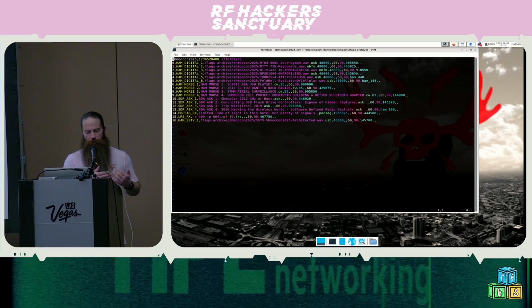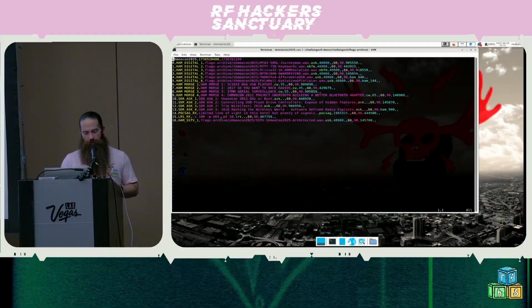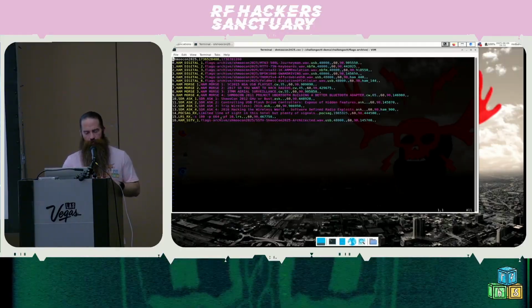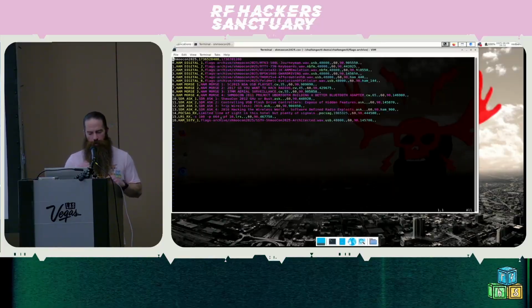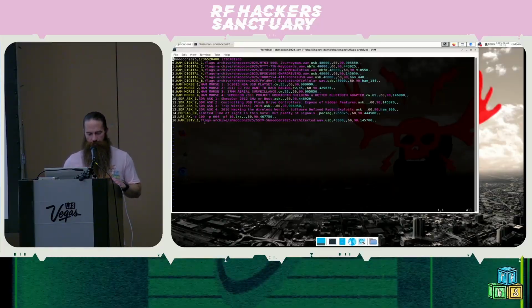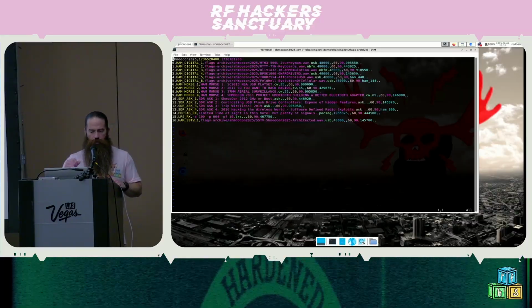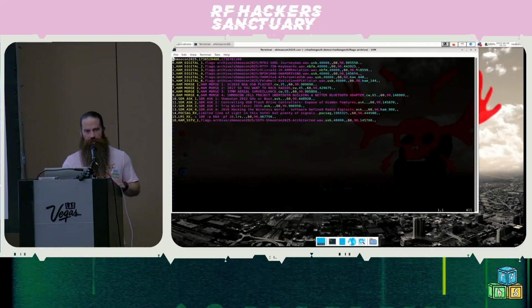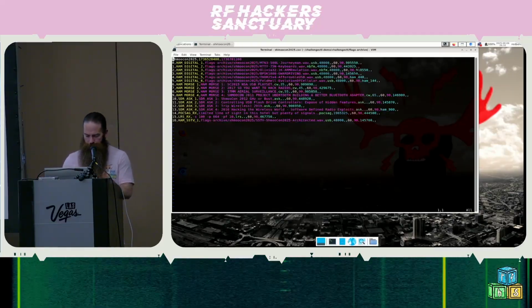So this is kind of an intermediate between generating a bin file or a wave file before running all of this. This script will generate the bin file on the fly and then transmit it out. And that's ephemeral, so that could be a little bit better. And then the SSTV is a similar sort of thing to the other digital modes in that we have a wave file that we generate, in that case with QSSTV or any other SSTV programs, and you plug it in there.